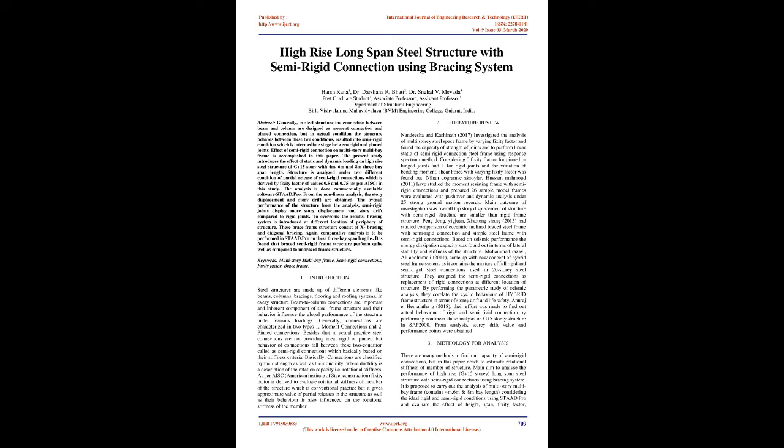in actual conditions the structure behaves between these two conditions, resulting in a semi-rigid condition, which is an intermediate stage between rigid and pinned joints. The effect of semi-rigid connections on a multi-story multi-bay frame is examined in this paper.